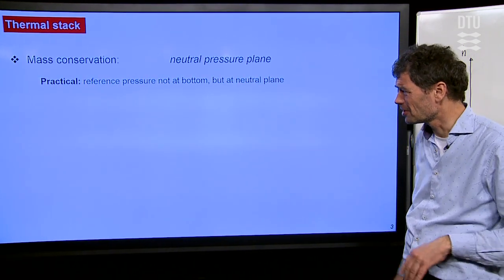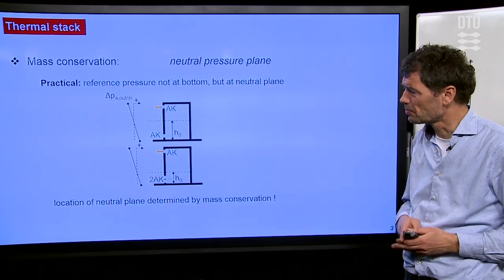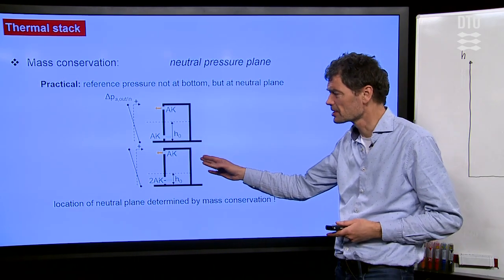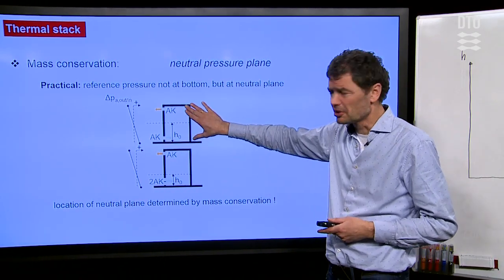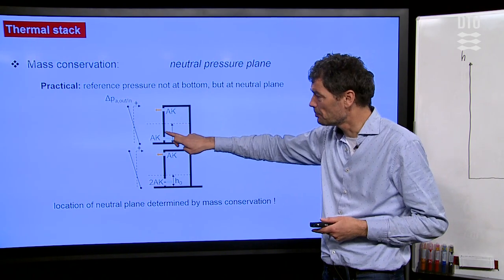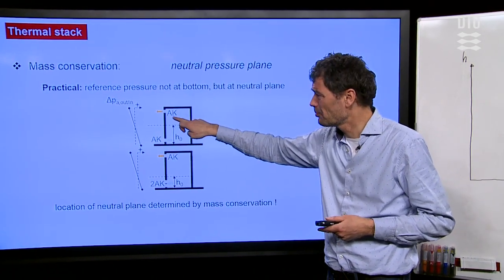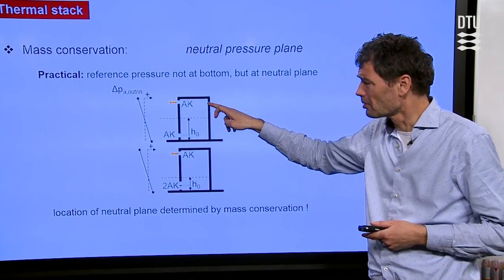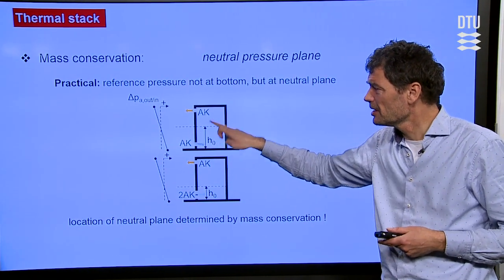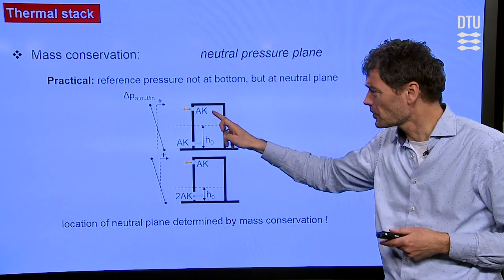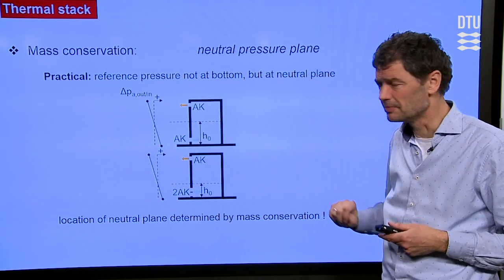Where should the air come from? So now we make it more real for a building. I showed two different buildings. The one that I have on the drawing on the top has an opening in the bottom of the wall and a similar opening with the same area and same air permeability on top of the wall. So air can as easily come in as it can go out on the top, in the bottom.